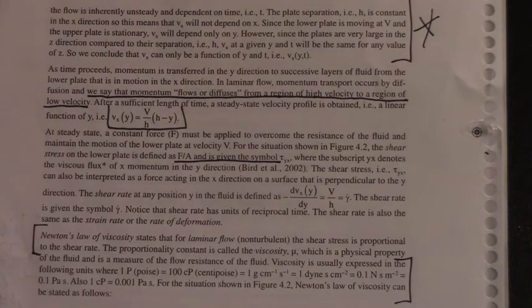Now what's interesting, if you did this experiment at home, you measured the velocities, you know the thickness of the plate, you got your shear rate, and then you measured the force that you had to apply to get that velocity and all that, and you did the shear stress calculation, then you'd say, okay, I want to take all this data that I've obtained at different plate velocities and plot it on a graph. I want to plot shear stress versus shear rate. What does my data look like when I plot it?